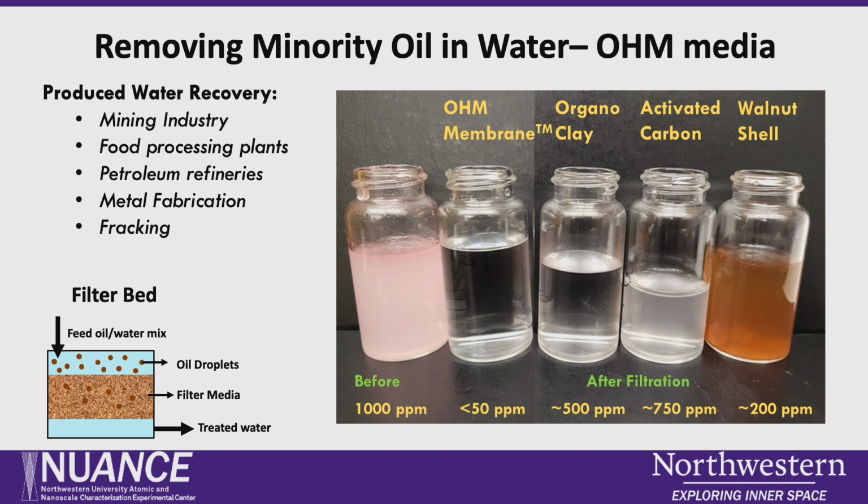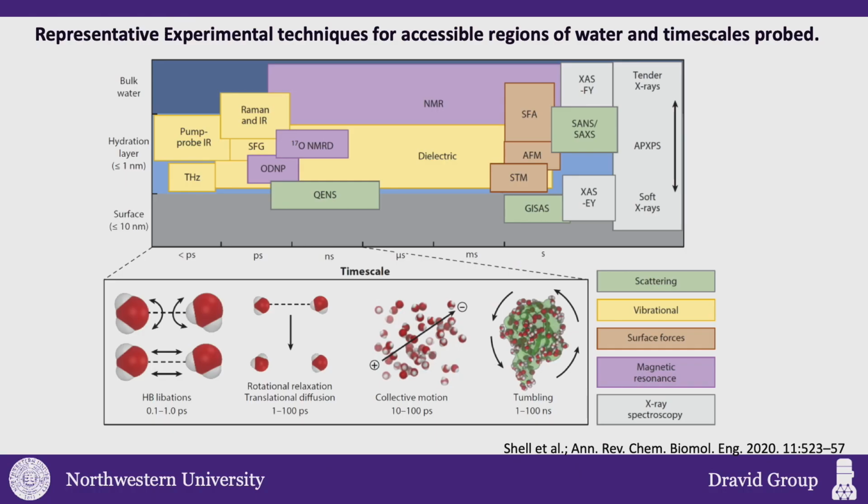So this is an example, again, of the same basic idea, but instead of polyurethane, which repels water, here is cellulose, which allows us to flow water through in large quantities. So we are talking about hundreds of thousands of gallons passing through the sponge-based system that we have, which is based on a hierarchical structure, in this case cellulose. And still, the same coating captures the oil and recovers it. So this is an example of a minority oil contamination in water, as opposed to an oil spill.